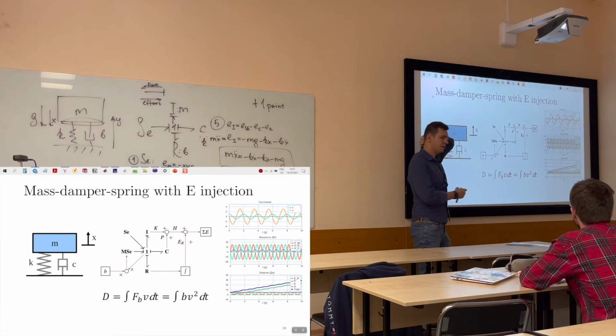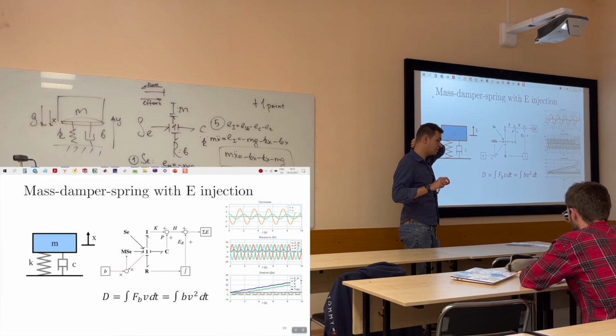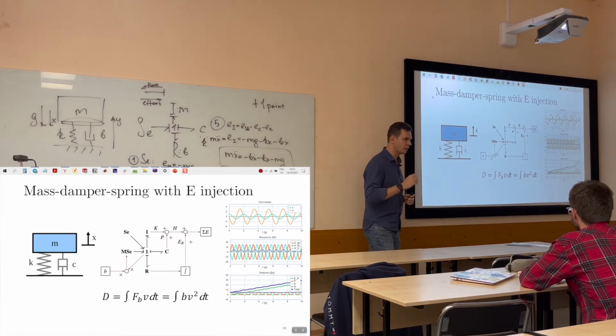And pretty much this is what we did with the hopping robot with Kirill, where we created the energy efficient controller that just computes how much torque needs to be sent into the system, such that we just compensate the energy that we lost for the contact. And this is why the robot is energy efficient: we inject just a little energy to compensate everything that has been lost to the friction and impact, to make it as energy efficient as possible.